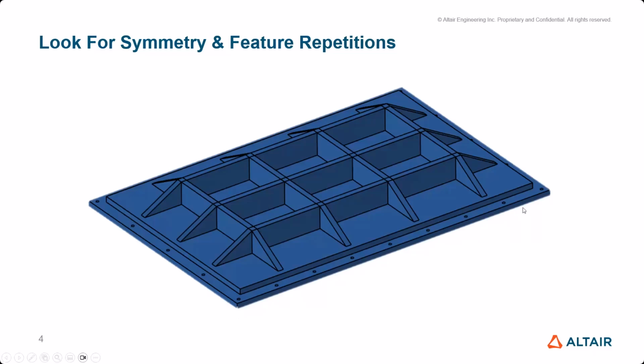You also have these fastener holes around the edge here, and if you want to keep those in your mesh, you might want to create a mesh that you fine tuned and you like around one hole, and then duplicate that and just kind of chunk out around the rest of the holes, so you don't have to redo that pattern everywhere. So when you're doing hex meshing, it's a little more time intensive than just a shell mesh operation, and so it can often be fruitful to take advantage of symmetry and repetitions.